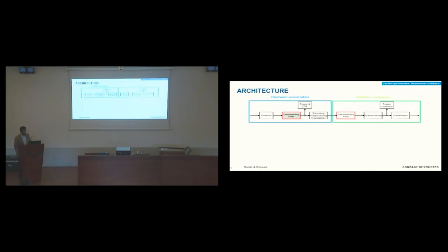So what is new here that we are showing today, and we will show you also in a demo later? The de-embedding procedure is performed in hardware just before the ADC acquisition. Okay? So the signal is digitized, then the de-embedding filtering is applied, and after that, with the signal corrected, we can trigger and perform the clock data recovery on this recovered signal in real time.